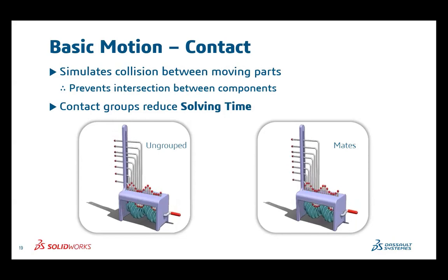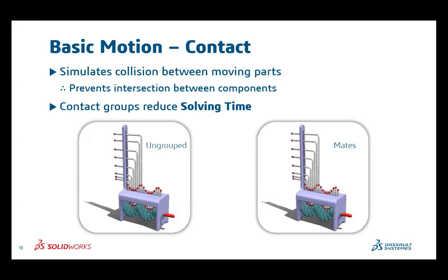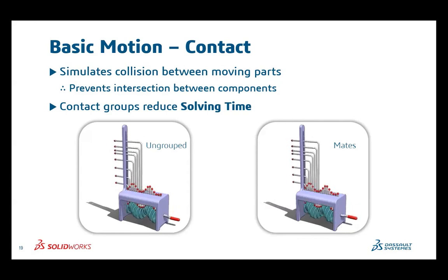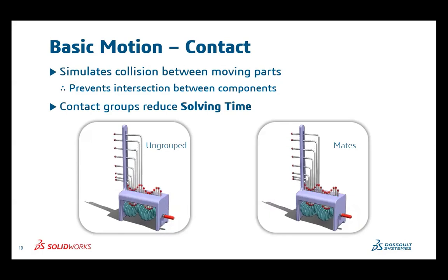And this is actually a question to you. If you want something that's realistic, then you need some simulation in it. You need some physics. So in that case, you would go with basic motion. If you want something that looks hyper cool, hyper realistic, and you don't want any hiccups, any friction, anything, something frictionless, no problems at all, no dust, no nothing, then in that case, you can use the animation. But this is not one solution or one fix for all, so keep this in mind.